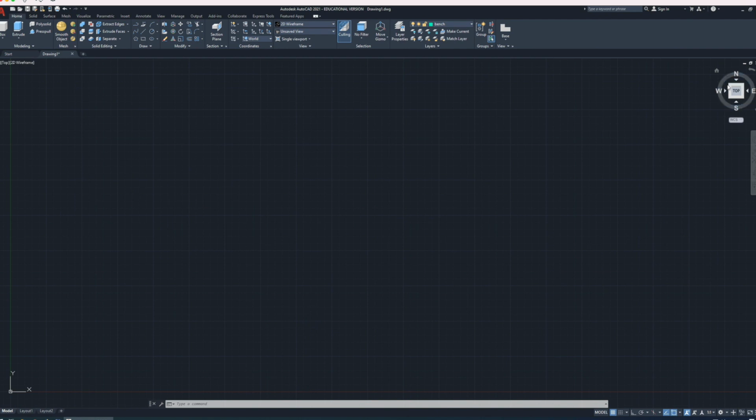The second thing I'm going to do is come over here to this view cube, and I'm going to click on a corner of it here. And what you'll see is it immediately pops into a 3D mode with X and Y in the horizontal plane and Z sticking up. And I'm going to swing this around until I get my x-axis pointing down and to the right, my y-axis going up to the right, the way we learned it in analytical geometry many years ago. I'm going to zoom out here, and now I'm ready to start drawing.